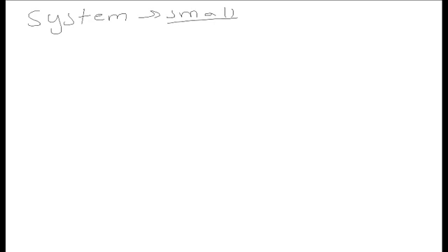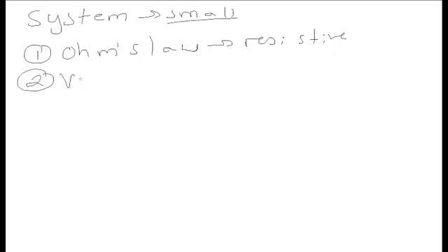So which laws do we have? Well, the first one is Ohm's law. At the moment, we're only dealing with resistive circuits. So really, the physical law that governs them is Ohm's law. From Ohm's law, we get voltage division, or VDiv to make things faster to write. Similarly, we have current division, or CDiv. These two are consequences of Ohm's law.